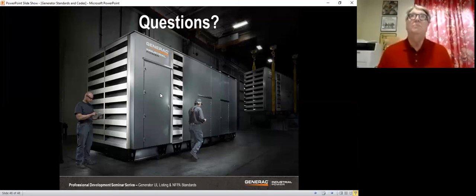Well, there's several ways of looking at this. For instance, if your tank has an incredible amount of rust on it, well, that might be a red flag. The biggest red flag is simply your reliability. If you find that that generator is having problems not starting, then that's a good red flag for wanting to update the generator. The reason why, frankly, I would say most people update their generators is simply time. They'll say, hey, this generator's 20 years old. I think it's time we replaced it.